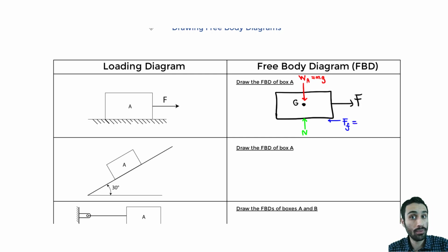And note the equation for frictional force, friction is fun, so it's going to be mu times N. Mu times N. And that N is actually the normal force, right? It's this. So that's the frictional force. It's like frictional resistance at the bottom here. You have some frictional resistance when we're trying to pull in that direction to the right. And that depends on the static condition. I just want to say the static coefficient, not kinetic, assume statics, and that should be given to you in the problem statement.